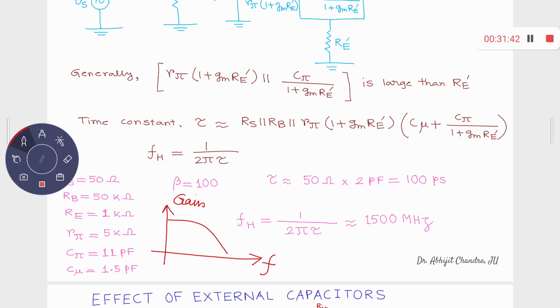Now, this particular frequency, hopefully you can remember, is known as the higher cutoff frequency, FH. So over here, this value is almost constant, right? And a point will come on the frequency axis where, if it is constant, that means it is at 0 dB, and then a point will come where it drops by 3 dB, and that marks the end of the pass band for a low pass filter. And we have identified the FH value for different types of amplifier: for common emitter we got some FH, for common base another FH, for common collector another FH, so different values of FH. But eventually all of them